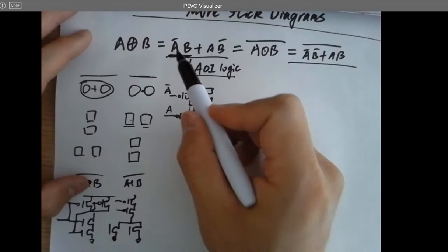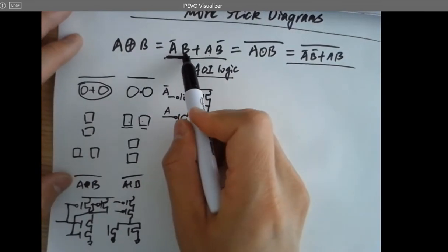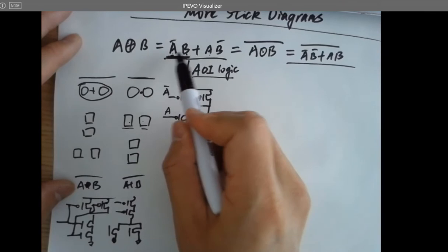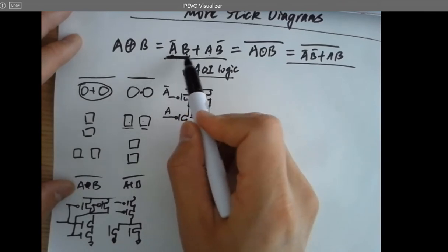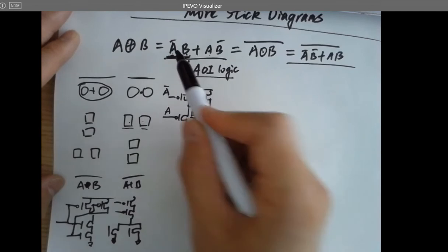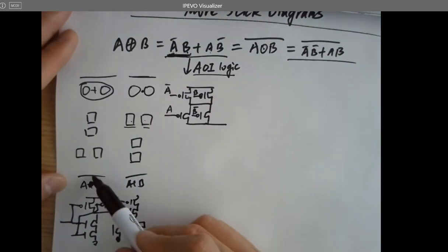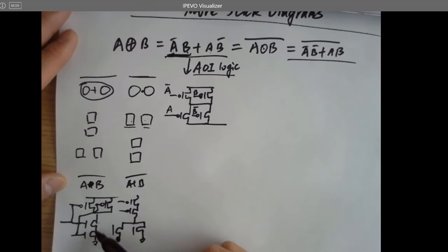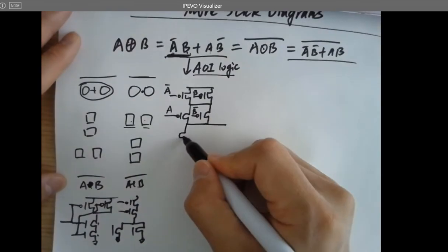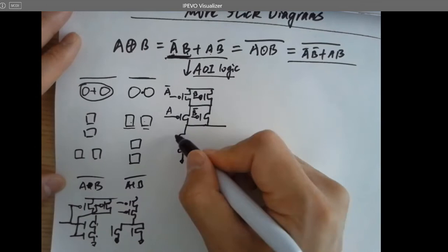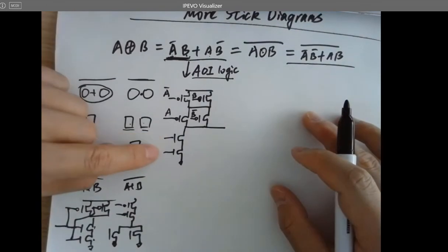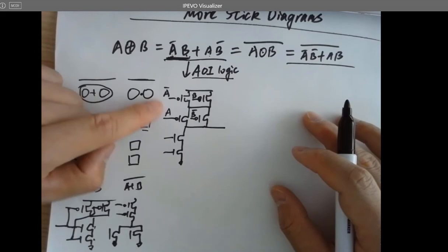And we still want to start from here. So since this is AND logic, for NMOSes, these two inputs or these two NMOSes should be in series or parallel. Always think about this AND logic for the NAND gate. NMOSes are in series. What are these two signals? A not, B.